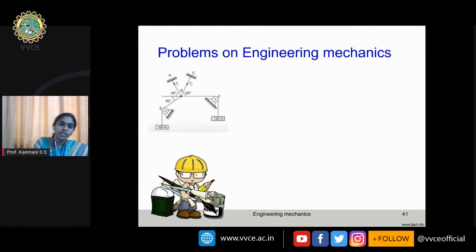See, when you have a frictionless pulley and a weight dropped here, because of this 100 Newton, this rope is under tension. That means force should move away from the joint, and this value is equal to 100 Newton. As it moves here, again this is a rope, it is under tension. The value is simply transferred, 100 Newton. Here also the rope, 100 Newton tension force that comes directly here just by applying summation Fy equal to 0.